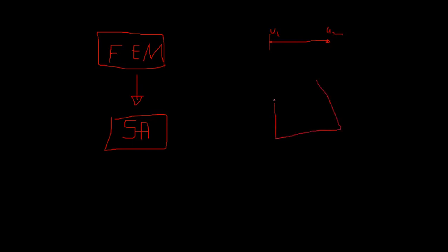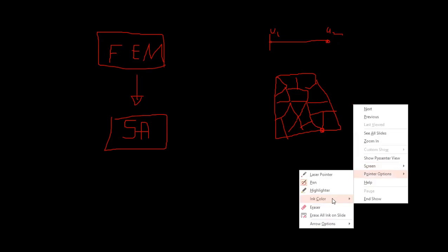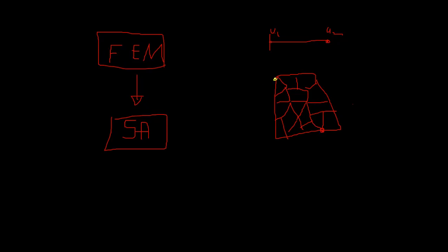But let's say it's like some tower, right? So you need to discretize it into several nodes. That means you need more finite points to solve this. So you need to solve whatever the forces or stresses are, which means you need to know at least some points, right? What happens if you have only 2 points? This is in no way giving you the correct results.